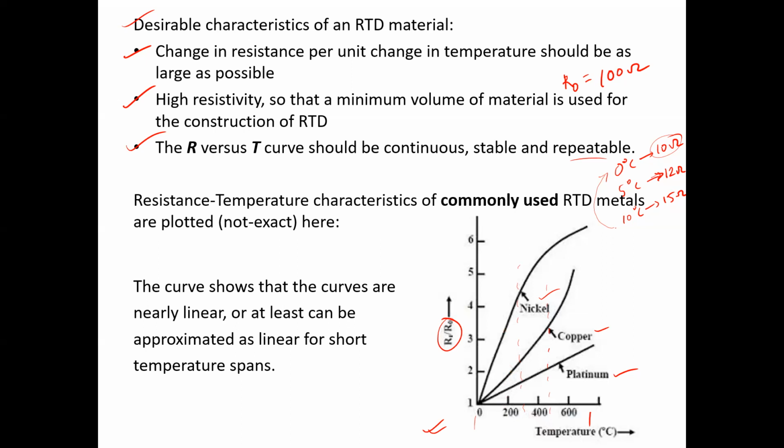So nickel and copper are showing a higher sensitivity as the temperature coefficient is higher than platinum. However, a trade-off has to be made so that a wide range of temperature can be covered for a wide range of applications, and also at the same time a relatively acceptable accuracy can be maintained.